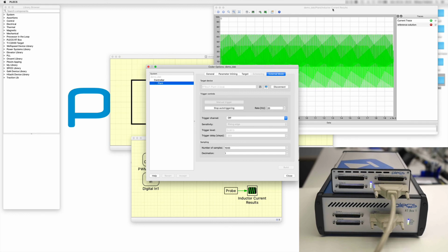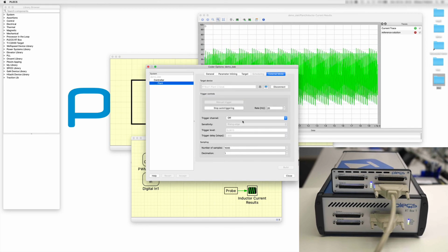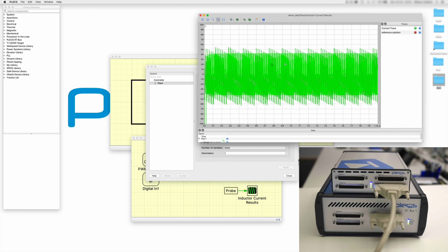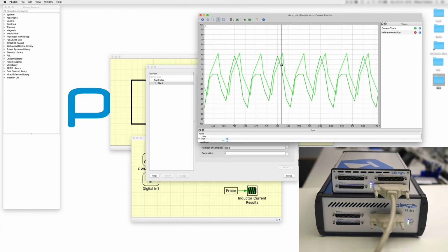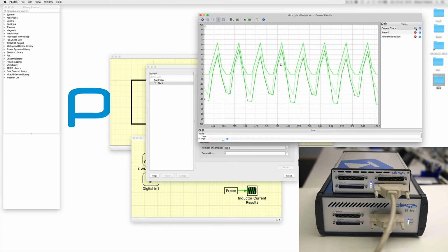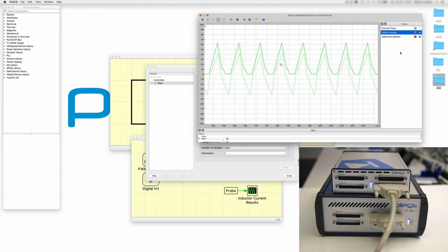And you can already see from this zoomed out view into the scope that the real-time simulation result we get with the hybrid module is absolutely inaccurate. So you can see that the positive or negative half cycles are not properly calculated because we do miss this switching of the diodes, and therefore we cannot properly represent this circuit in this operating point. I save again a trace and call it the hybrid module simulation result.